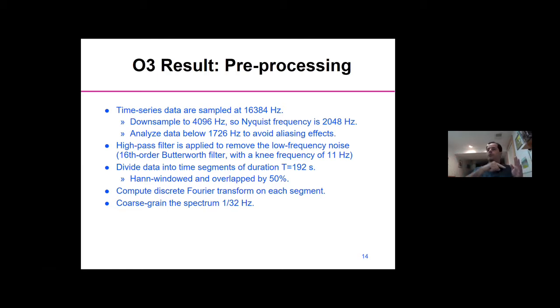So to avoid that, we apply a window that basically zeroes the beginning and the ending part of the time segment, and then do the analysis of this windowed data set, or segment, which is better behaved when you do Fourier transforms and so on.